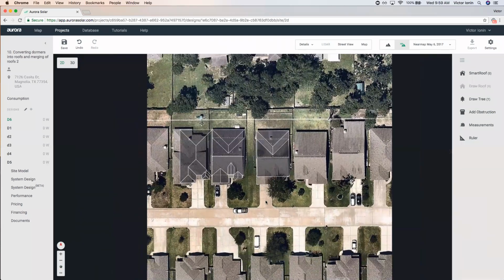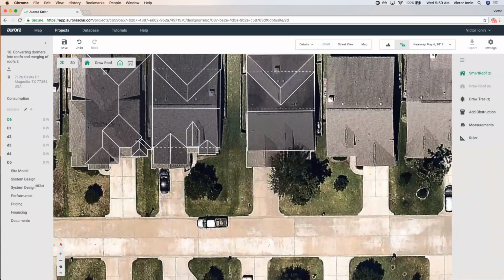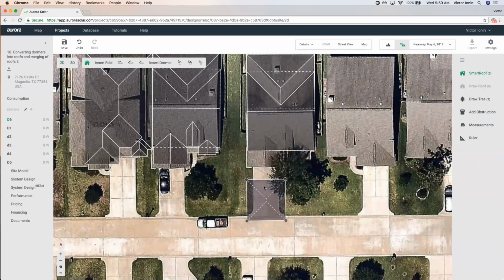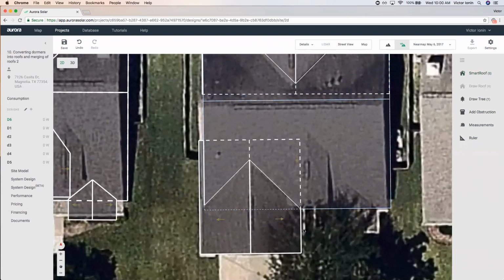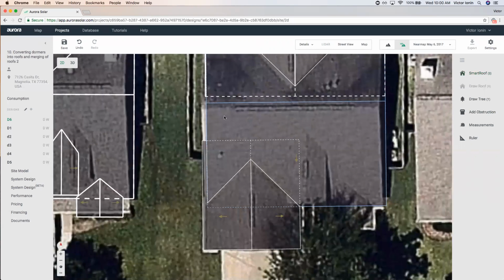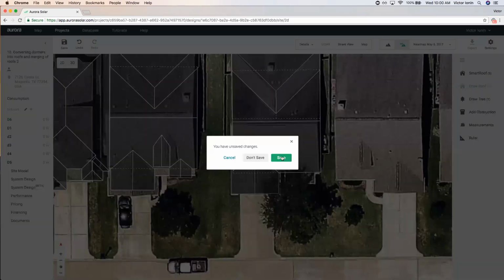Let's do it for the garage. Here, I'll show you what I'm doing. All I'm doing is drawing a box. The garage has a west face and an east face, so let's go ahead and get rid of the north and south. Exit the edit mode, click and drag, drop it in place. May have to resize this a little bit, but there you go. You can see that the software knows that part of this box is underneath the south face. So you see the dotted lines, they're going to be hidden. So when you go into 3D,